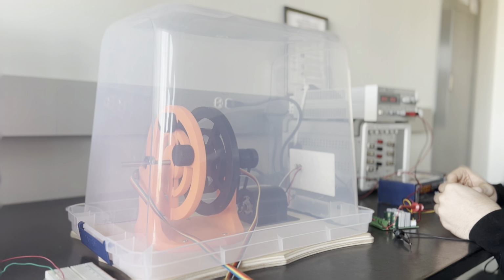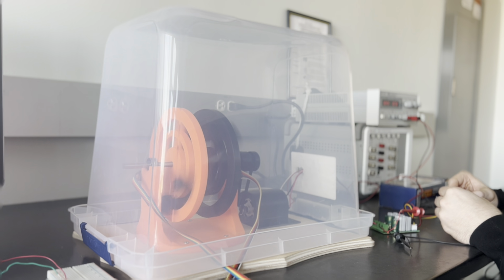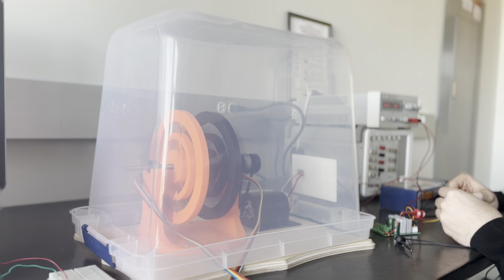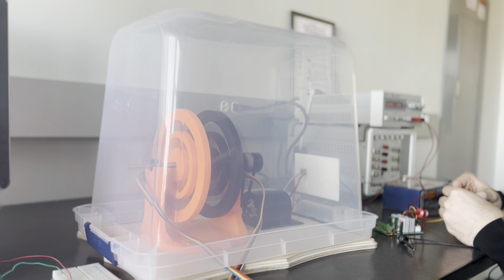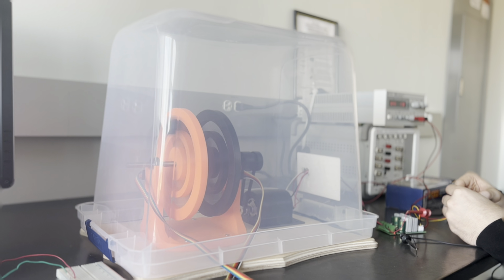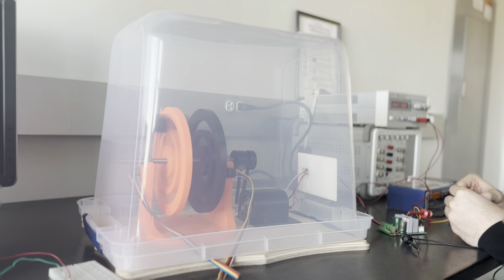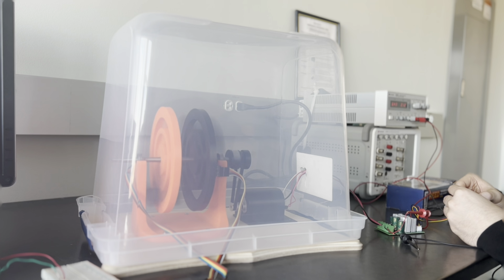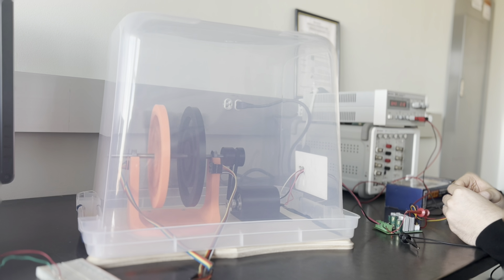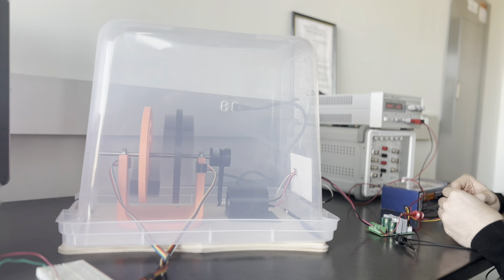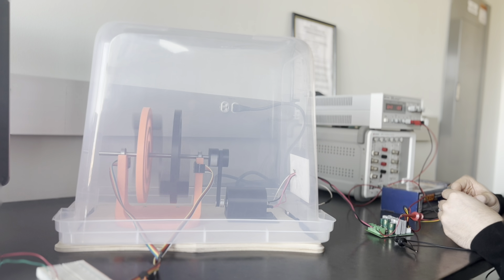For a system to be dynamically balanced, there must be no out-of-balance centrifugal forces trying to deflect the shaft and no out-of-balance moments trying to twist the shaft. As seen in this demonstration, the masses are opposite each other on different planes, causing both twisting and deflection of the shaft. When the motor is spinning at 1300 RPM, the vibrations due to these unbalanced forces can be seen. The system vibrates and moves across the desk while the accelerometers attached under each bearing pick up and record these vibrations to later be used for balancing.